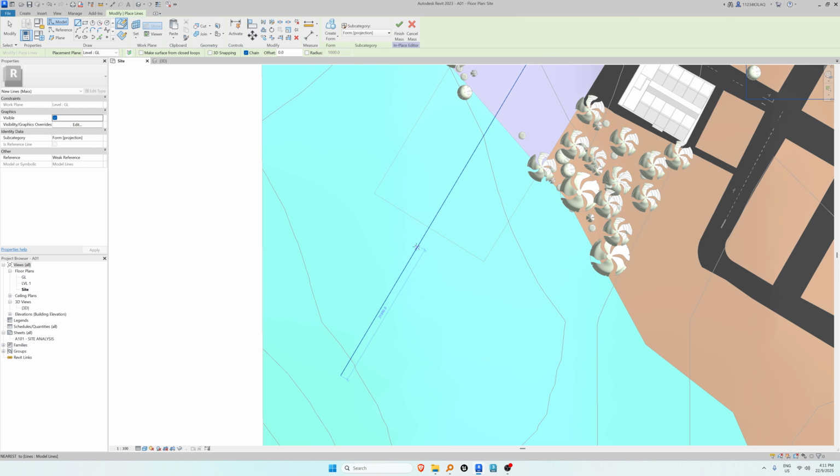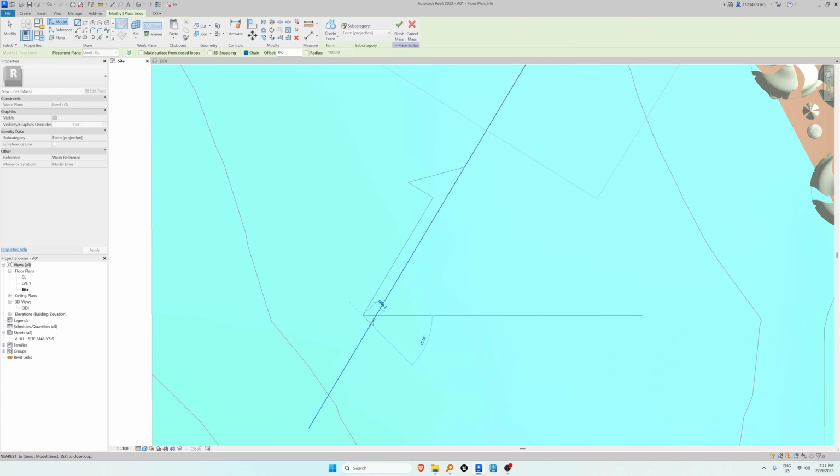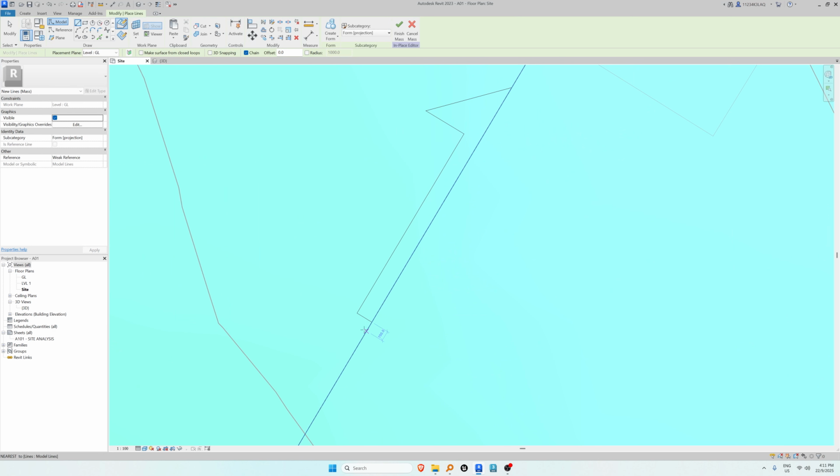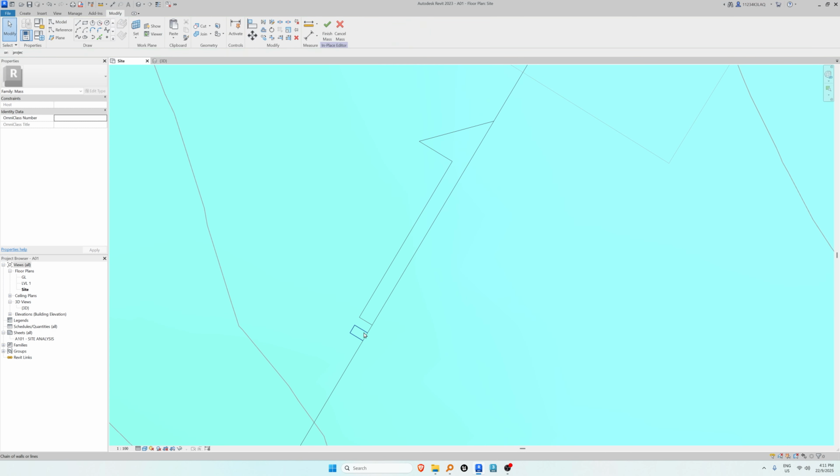So now what we're gonna do is we're gonna make an arrow. Okay, or half an arrow. So something like this, this, and this. Okay, make a box here, and then select it, copy it, CO, pick the base of the arrow, place it here, maybe one more. So now you have 3 rectangles and half an arrow.